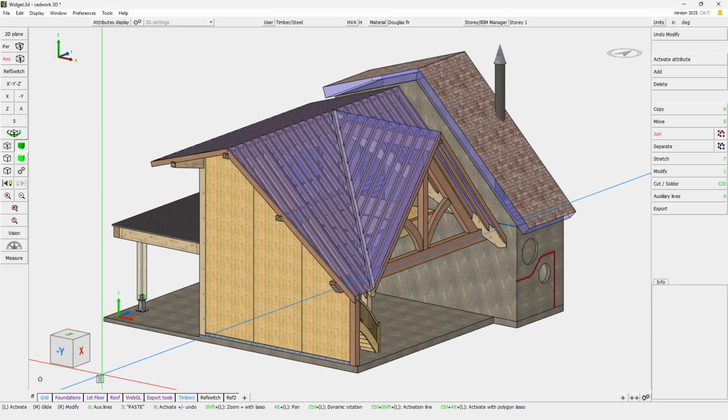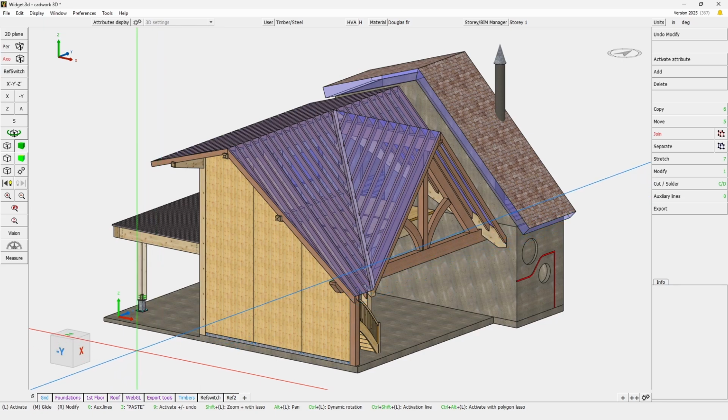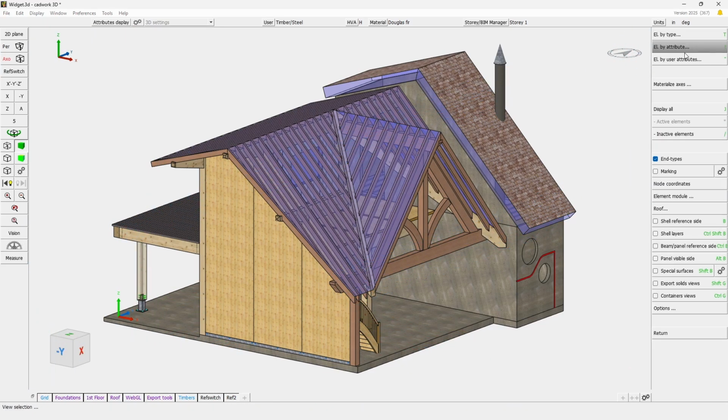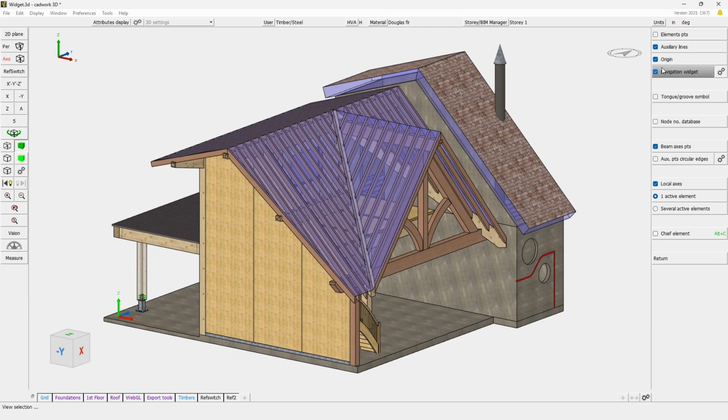If you were to deactivate all of them and wonder how you can actually bring them back, when you go to Vision, Options, and Navigation Widget, you can here turn them all off, or simply, using the cogwheel, activate or deactivate any of them.